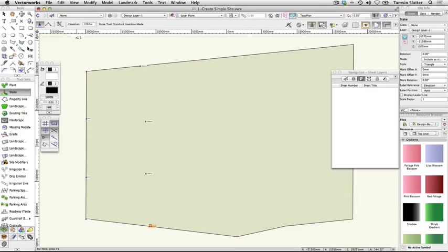On the toolbar, change the elevation to 2500 mm. Roughly halfway along the shape, place another vertical arrangement of 4 stakes on the polyline. On the toolbar, change the elevation to 3000 mm and place a further arrangement of 4 stakes, roughly 3/4 of the way along the shape.